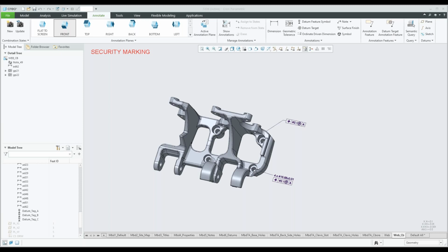Take a small project, test drive it, see where it's going to work for you. Check the standards that you currently have in your 2D drawings. Can you apply that in a 3D model? And then beware, there are people that still want the 2D drawing. They've learned how to read them. They read them pretty good. Moving away from that to 3D drawings or 3D parts, now all of a sudden they have to use Creo View to go and measure things or find information. So it's a different way of working.